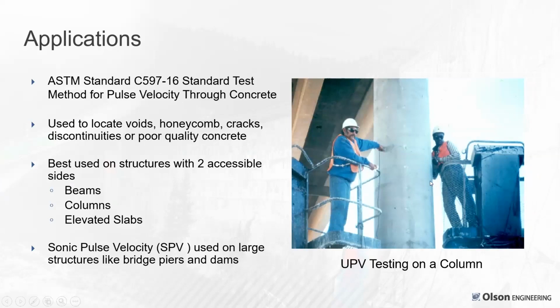But here is just a bridge column that had some issues with honeycomb void being tested on a 1-foot grid, north-south and east-west, with light lithium grease spots. Relatively non-staining. If you're really worried about staining your concrete, you use an ultrasonic industrial or medical ultrasound gel, which is non-staining. But here we were looking at how much honeycomb was present. So as mentioned earlier, the sonic pulse velocity test is used on large structures like bridge piers and dams.